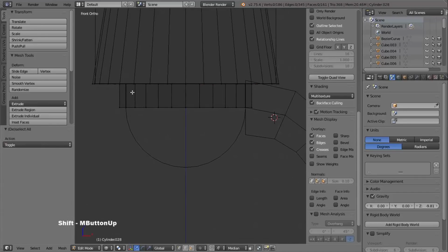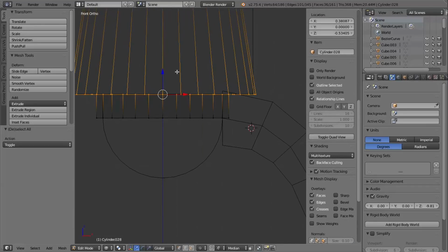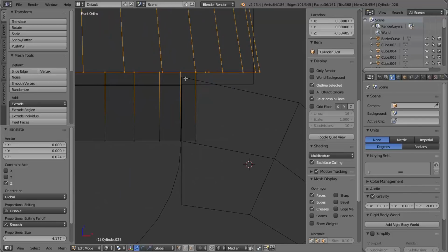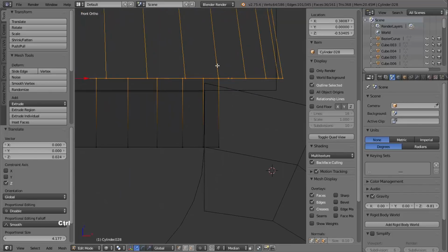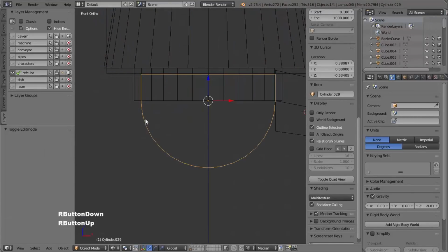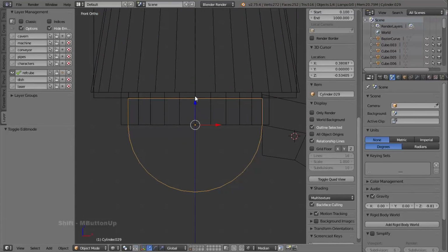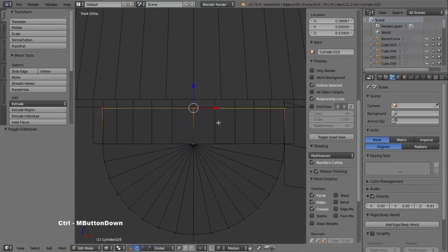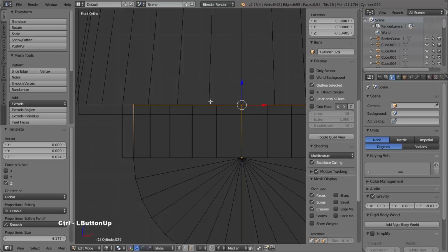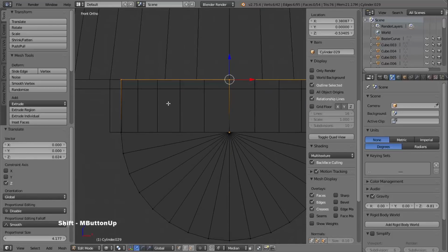And I want to drop my current selection and box select all of the vertices here. And then I just want to move those up so that they're just above this corner of the claw so that there's a bit of clearance. And if I go back to object mode and select this hinge object, I've got a similar issue there. So I want to go into edit mode again, and I've still got my vertices selected from before, and I can hold Control and click on the blue arrow and then just snap that up to the top again.